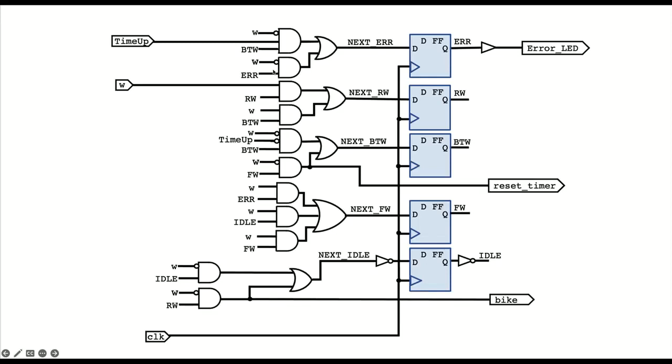Okay, yes? Is that triangle supposed to be a NOT gate? No. Okay, so you may see these things in here. These are just plain buffers, and in a real circuit, a buffer may have some electrical reason to exist. But in terms of logic in your schematic, the purpose of a buffer is to allow you to change the name.